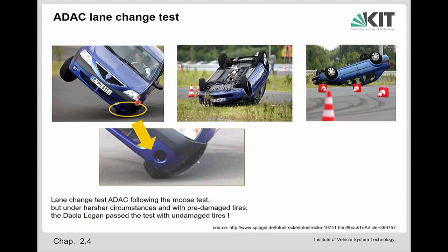It's only standing on the outer side, and this gives such a strong deflection of the wheel. Relatively, the wheel comes very close to the car body. So there is this end stop, and if it hits the end stop, this is an extra force in vertical direction to the road. So we have a super high friction force which can be transmitted, and then the rollover takes place.